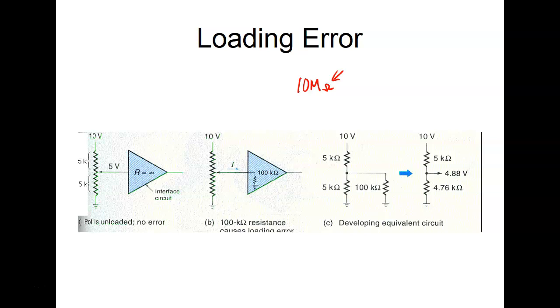And the problem is the actual resistance changed depending on what voltage scale you had on. So the lower the voltage scale was, the less resistance the meter had. So basically, it was nothing but a voltage divider. So when you switched the switch on that one, you just switched to a different voltage divider. So real interesting. So here's using this Simpson 360 when we shut down the line. That's another story.